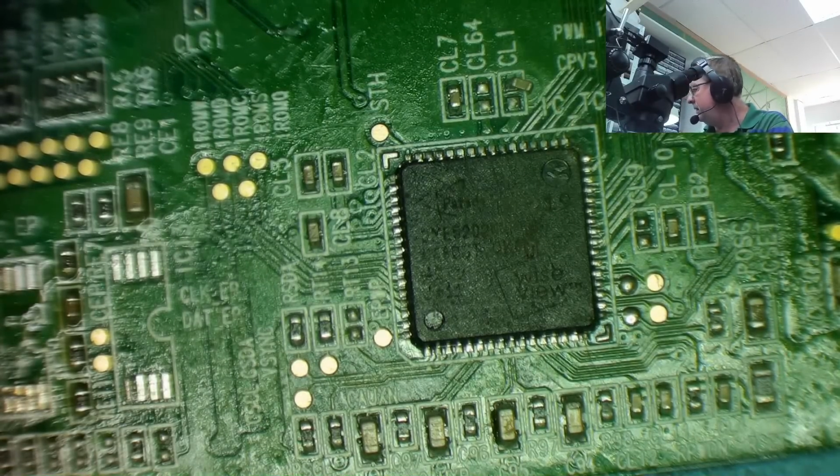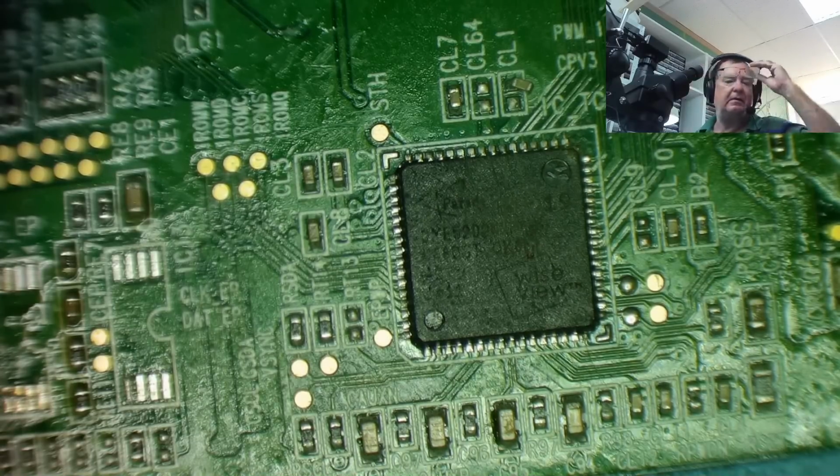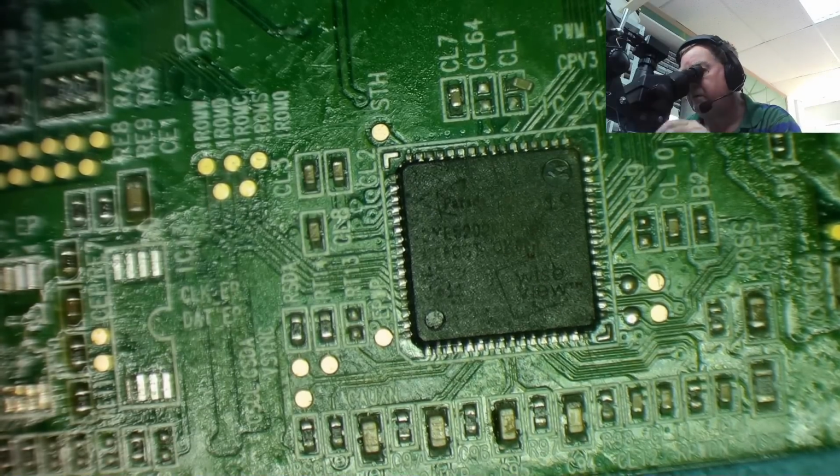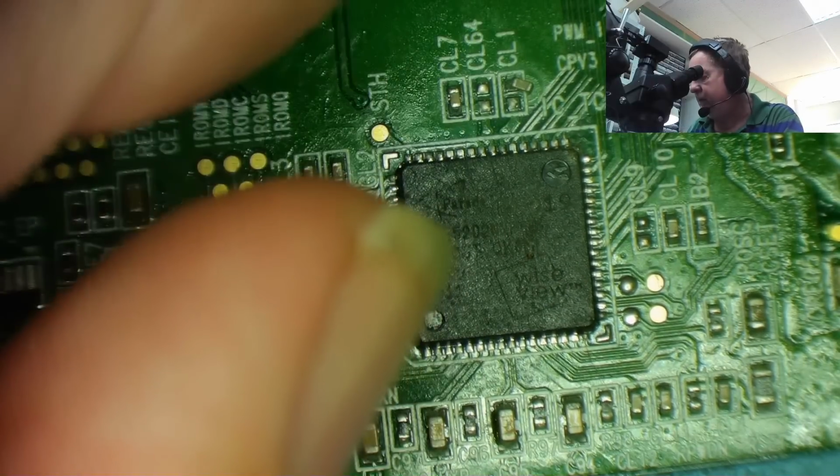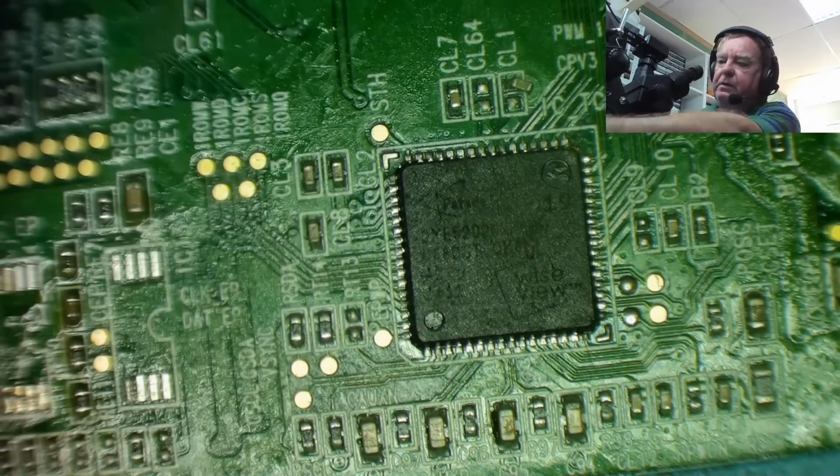Okay, so yeah, I'm thinking we might be able to solder this just using the soldering iron. I've got some of the thin solder. I've got the VC3 tip on, the big chunky one. Let's have a look down this microscope and see what we can do with it. So first of all, the knack is to get the thing to line up. That's fairly close. I don't think it's exactly, but it's fairly close.